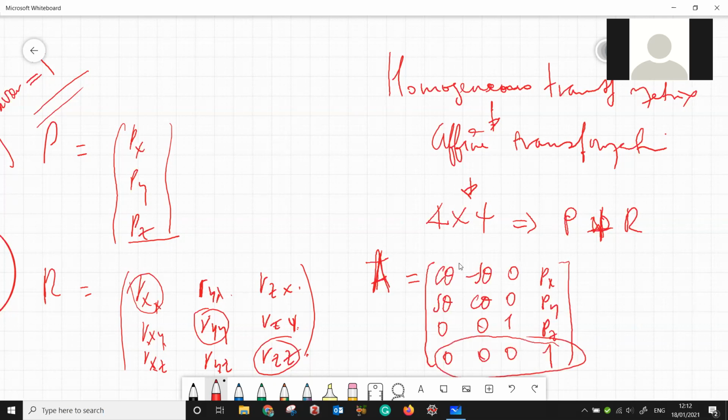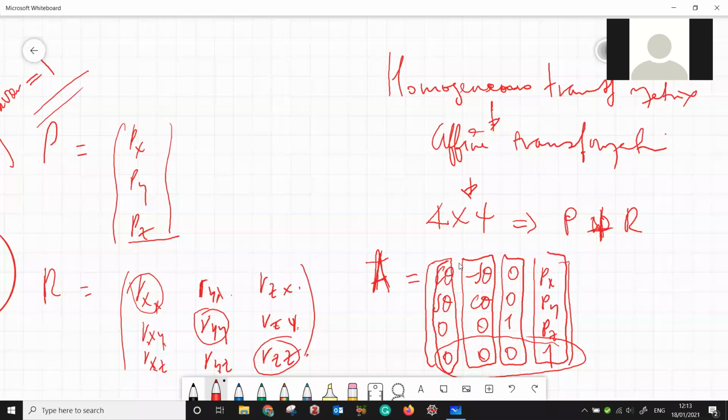So that's the idea. A homogeneous transformation matrix in general consists of the rotation matrix about X, about Y, about Z, and the position vector along X, Y, Z. This is called a homogeneous transformation matrix. It represents the combined position and rotation vectors and matrices in a single matrix. So this single matrix can represent the position and orientation of a single joint with respect to the other.